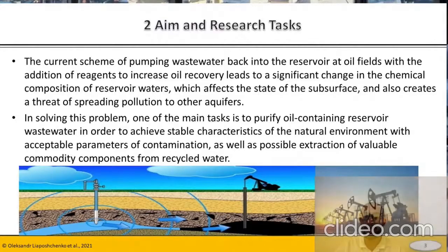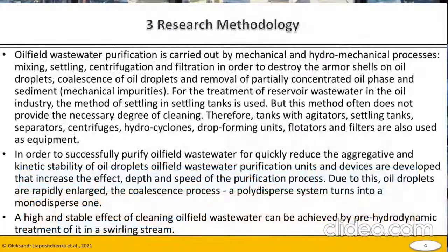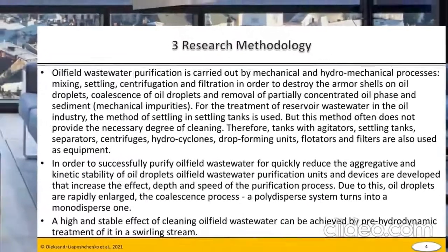Oil field wastewater purification is carried out by mechanical and hydromechanical processes, mixing, settling, centrifugation, and filtration, in order to destroy the armor shells on oil droplets, coalesce the oil droplets, and remove the partially concentrated oil phase and sediment.